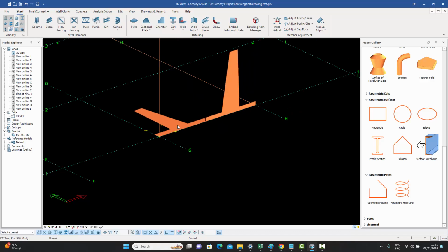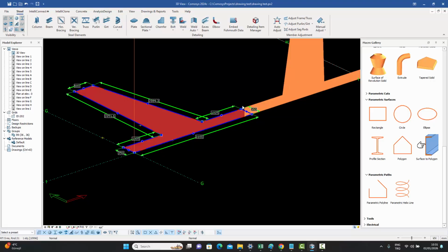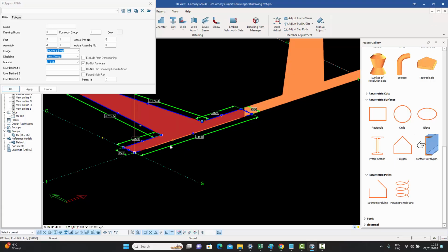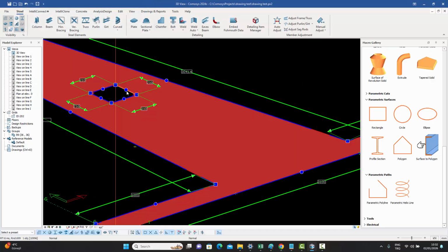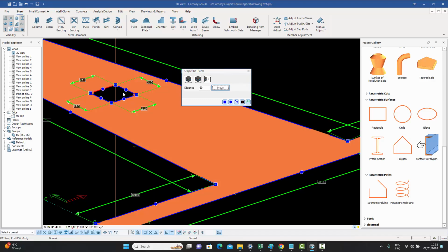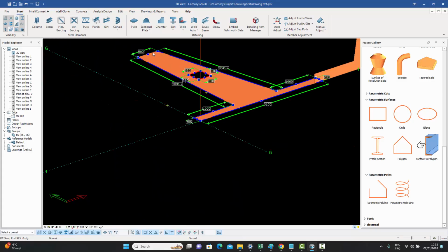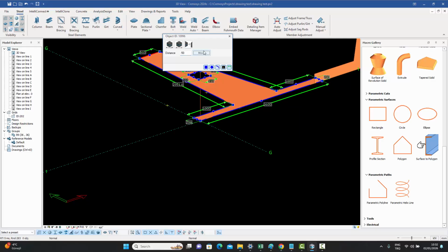So this really gives you an advantage, because the modification of an existing general shape is a lot easier than entering the general shape from scratch. So what we've done is we've added this feature. You can now create a simple square if you wanted to, and then go to your library of shapes. Just load any shape which you want. Just say load, and it will be loaded, and then you can maybe make the hole bigger. If you wanted to, you could just go in there and select the sides of the hole like that, and make it bigger, make it shorter, make the whole retaining wall shorter like that.